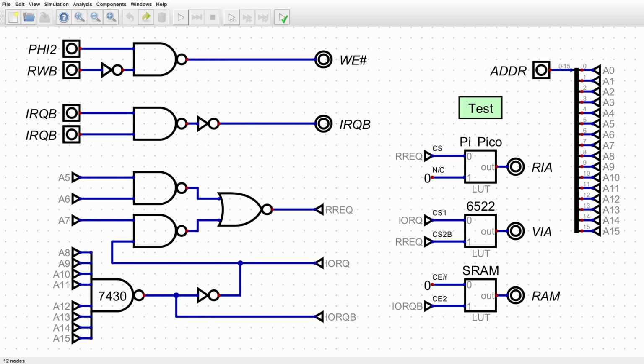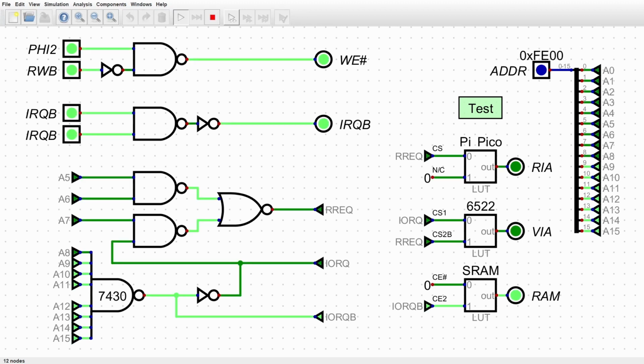We're using 3 chips for this logic. The design was 4 chips for a while. The last bit of optimization was to incorporate the address decoding logic built into the 6522. Devices with multiple select lines have internal logic to combine them, which we can take advantage of. It'll be easier to see in the simulation. This is on GitHub if you want to run it yourself. I'll run through all the boundaries now. I won't talk through the gates, so pause and rewind if you want to study the logic on the left. I'll describe the test on the right. RAM starts at address 0.